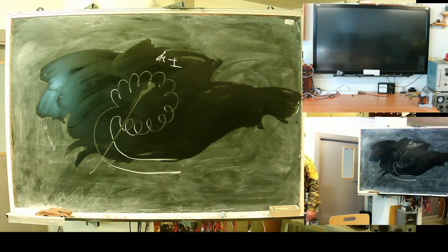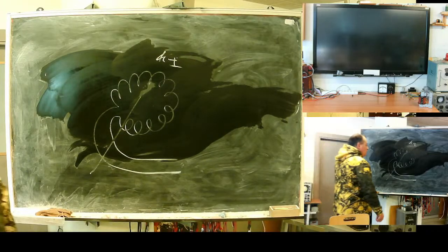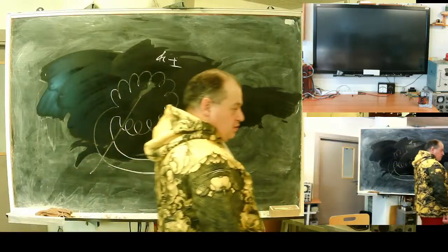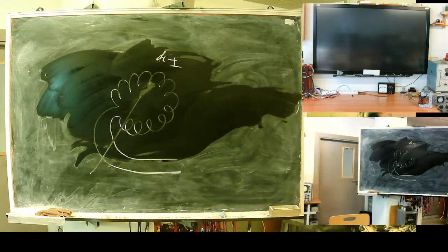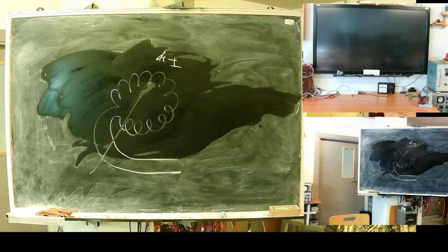The Rogowski coil doesn't have a core, doesn't have a magnetic core. It needs only a coil form for mechanical strength. And there is one thing: the Rogowski coil is very linear, but it has near zero load capability. It can be loaded. And the Rogowski coil produces the first derivative of the signal.